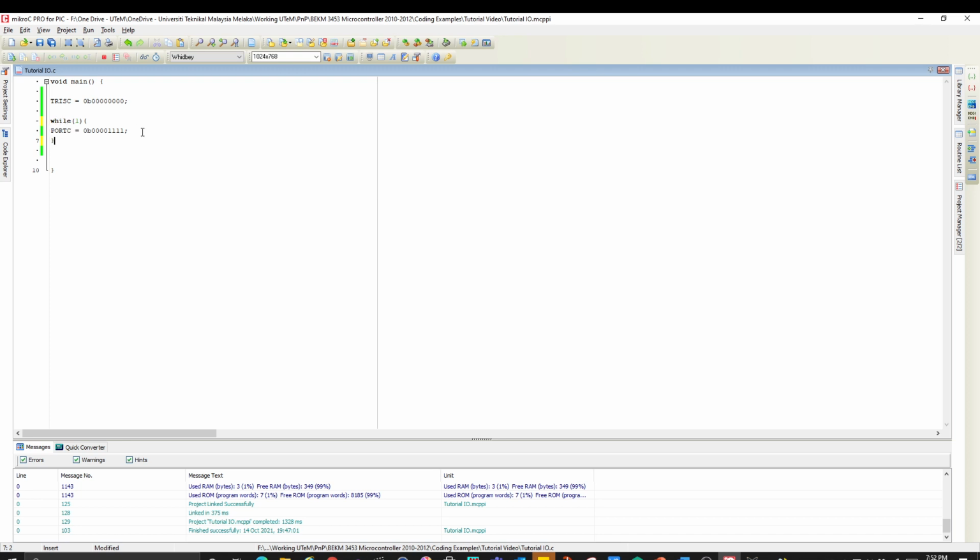Just want to show you how. So we can do a blinking LED. So right now you can put delay ms, like 500 milliseconds, right? Then semicolon, and then you can turn on this one and then you can turn off this one. Alright, so we can just copy all these things and then we change this one 1111, and then we change this one, the last 4 is 0000. So this command will do the on and off.